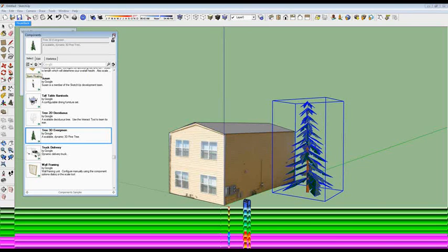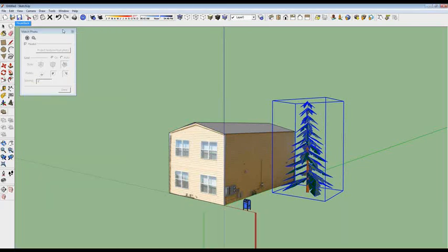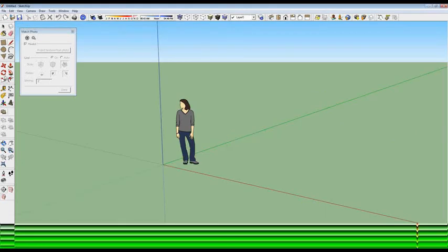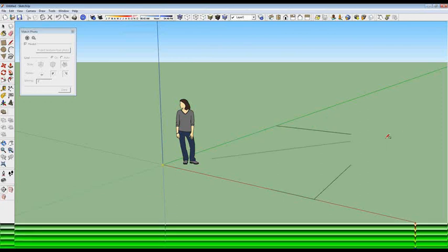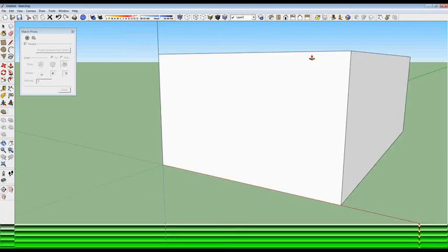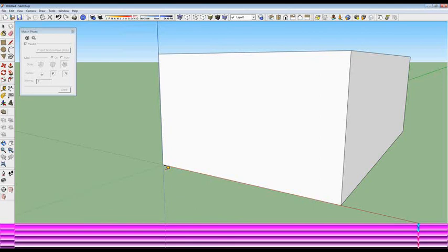If you are taking this into more of a construction phase or more into the documentation as opposed to the way that I've kind of been showing it here, just very conceptual, you can take and use several of these other measuring tools to become much more accurate. So again, we can take and just draw a general box and make it as tall as we need it to be, but we can actually specify distances with this as well.